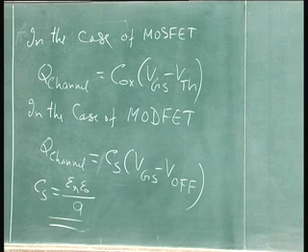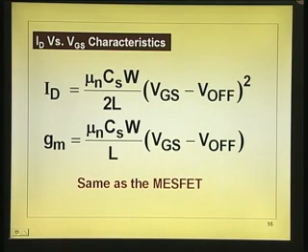So, when you go to the HEMT, you get transconductances which are larger due to higher mu n. In the case of silicon, how much is mu n? Surface scattering is dominant, about 1000 centimeter square per volt second. In this case, it is about 8500 at room temperature, 8.5 times larger, and CS is about 3 times larger for the same A, same thickness.